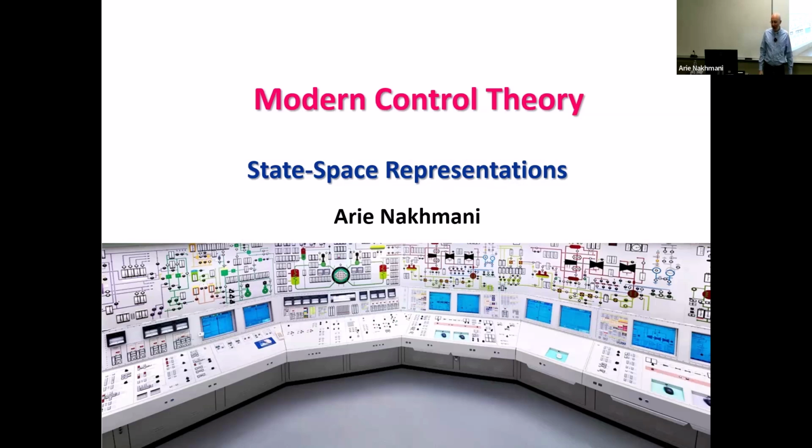Okay, to remind you what we learned previous time, I described in the previous lecture state space representations, and we went through explicit representations for SISO systems, for MIMO systems, discrete time, continuous time systems. I showed all these block diagrams that you can get from these representations. We learned a little bit about stability.